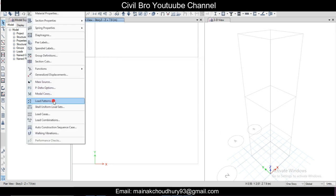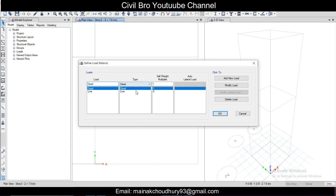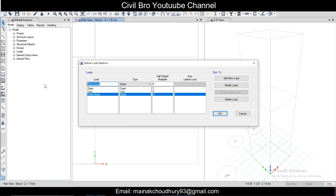So we'll go to load patterns. Here the dead load is there. In this dead load we will put the self weight, and we'll take another dead load in which we will not put the self weight, so we will put 0 here. I'll do other dead. In this dead load we will provide all the floor finish load, load of the walls, etc. Then add new load.